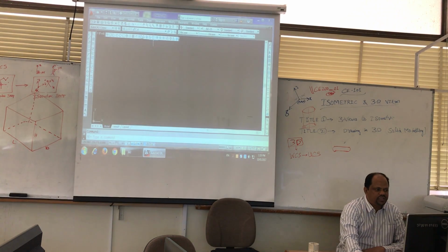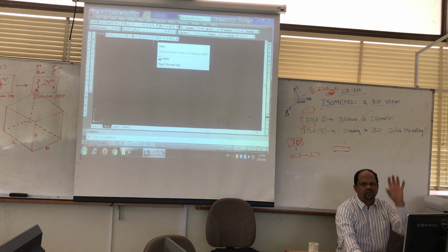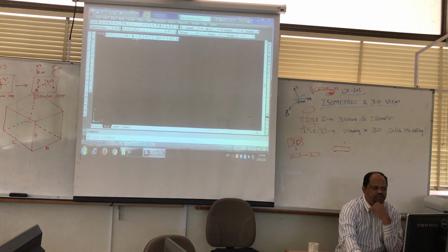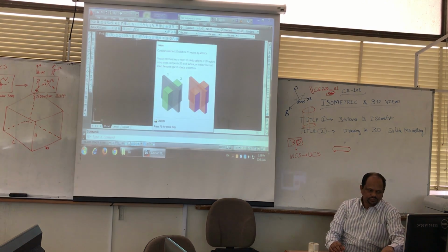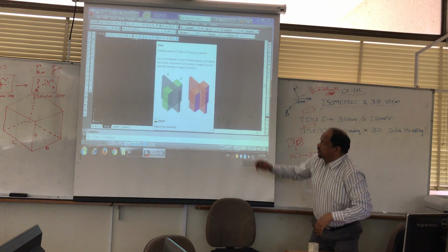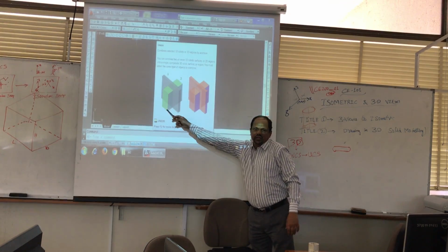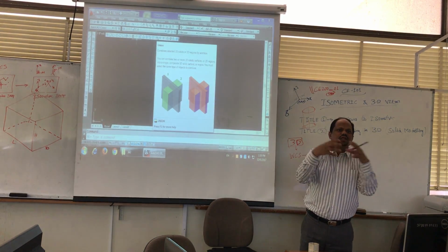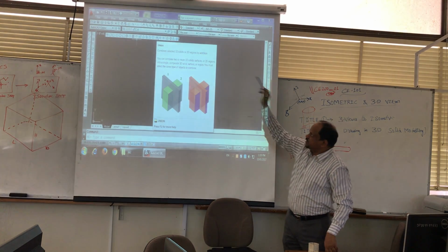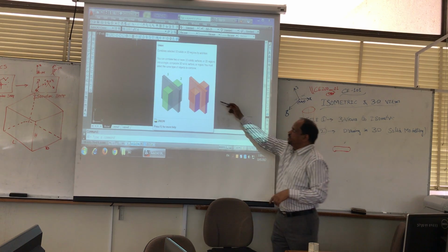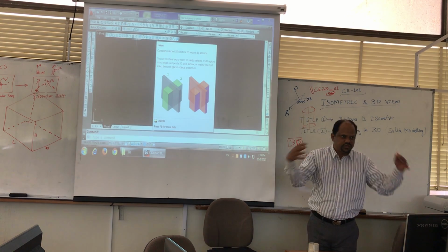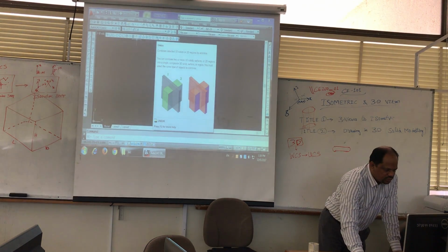Now, after this, because we are doing the basics, I will just tell you about another command. This is the union. Union means combine two objects together. You draw one and another. You want to combine, union them together, means add them together. So select the union command, then 1 and 2, then press enter, it will make it as one object. This is called union.